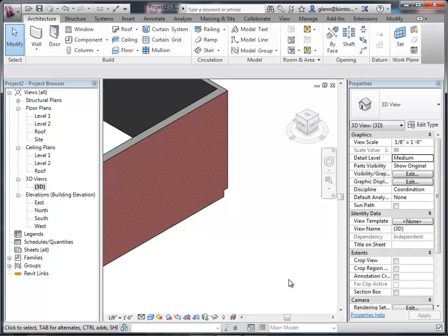Now, that isn't necessarily so useful. Sometimes I do that around the outsides of buildings. When I have level 1 here, and I actually want this siding to continue down and cover the subfloor, I'll sometimes put a negative offset at the bottom just to get the siding to wrap down further. Okay, and that's kind of a cheap and easy way to do something like that.